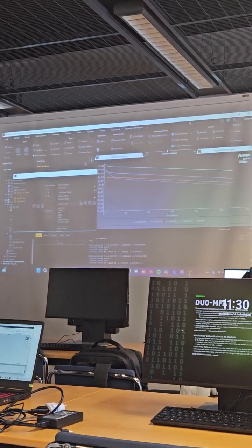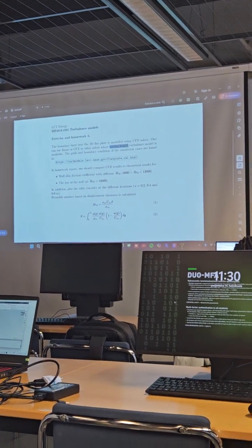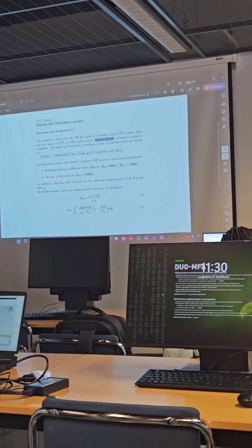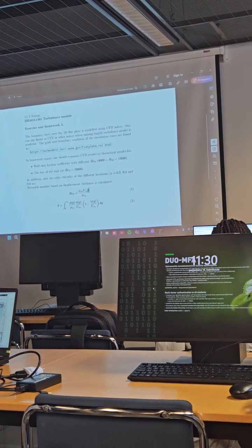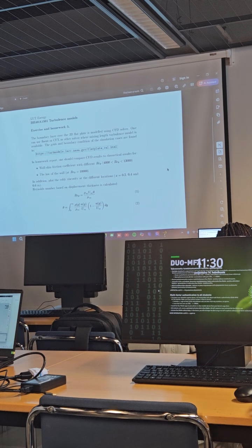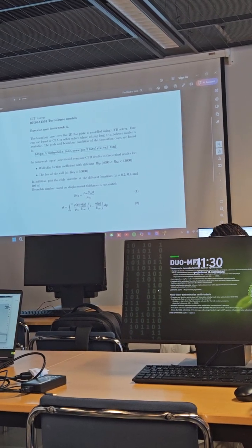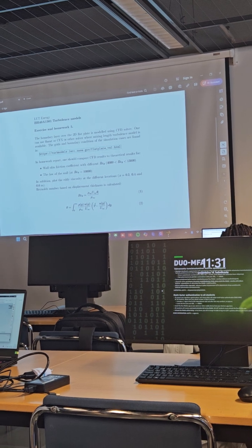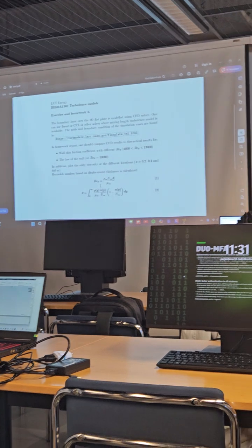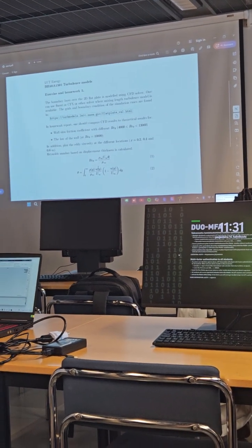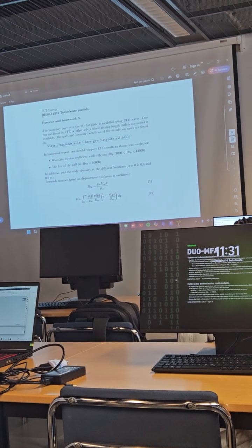Okay, and then next, since we need to calculate the wall skin friction coefficient for Reynolds theta, and Reynolds theta depends on theta, the displacement thickness, we need to know the distribution of density and velocity in the boundary layer. The density is almost constant, since this case is incompressible. Instead, we have a variation of u as a function of y along the boundary layer.